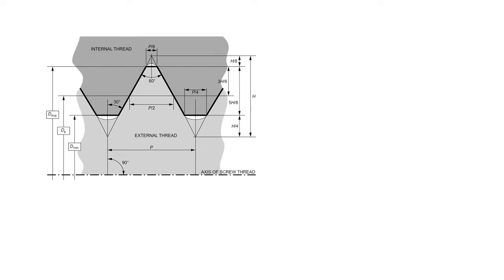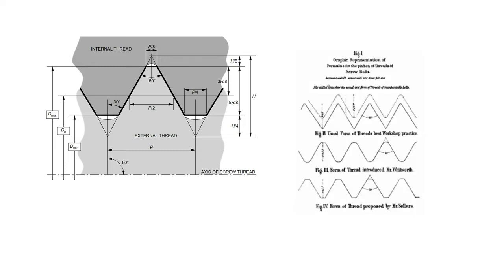We'll see more well-rounded edges in caps of the water bottle that you use or the pill bottle that you're taking because they're manufactured with injection molding instead of machining. Thread shapes, however, used to be like a V shape as shown on the right. They have been modified to trapezoidal shape over the years, and that has allowed longevity in screw threads.